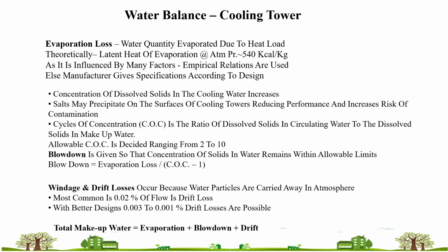So that is windage or drift loss, we can say, from the water dropping to the basin. From the inlet air opening, the water molecules always pass to the atmosphere if your winds are on the higher side, or you are facing some turbulence-like situation. So water is always getting passed to the atmosphere, so it's another loss